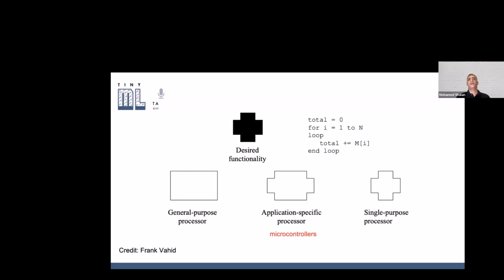the application. But the problem is, from the economical point of view, it's very hard for microcontroller vendors to provide a microcontroller for every application out there. So what they are doing is they create families where every family targets a class of applications, and then in each family we have members. As an embedded application designer designing an application using microcontrollers, you select the vendor, and then you select the family based on the application that you are targeting, and then you start to pick one of the family members that fits the application perfectly.